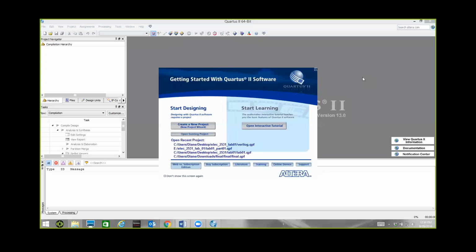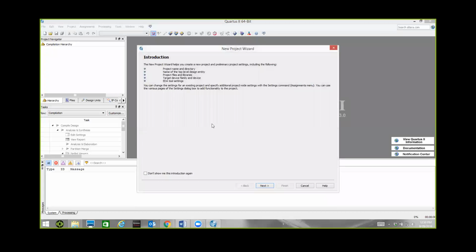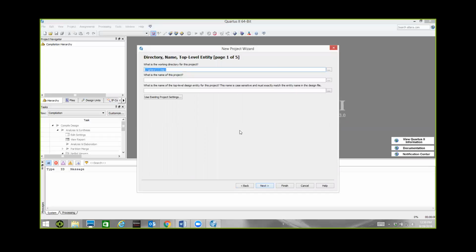All right, so I've shifted over now so that you should be able to see this screen where Quartus popped up. You shouldn't have anything like this menu at the top. That's for our recording. But notice here, Quartus pops up, and I want to select Create a New Project. That's the step we were doing. All right, New Project Wizard. We just don't pay attention to the screen. We just hit Next for introduction.